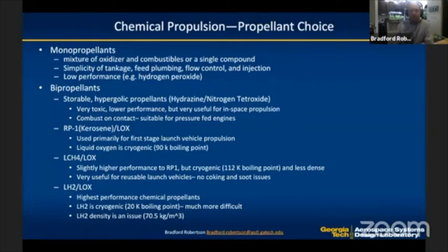Monopropellant, such as just hydrazine, right? That's a mixture of oxidizer and combustibles in a single compound. So it's very simple. It's usually pressure fed. I just have simple tankage, but unfortunately, it's very low performance. And so that's kind of the trade-off there.